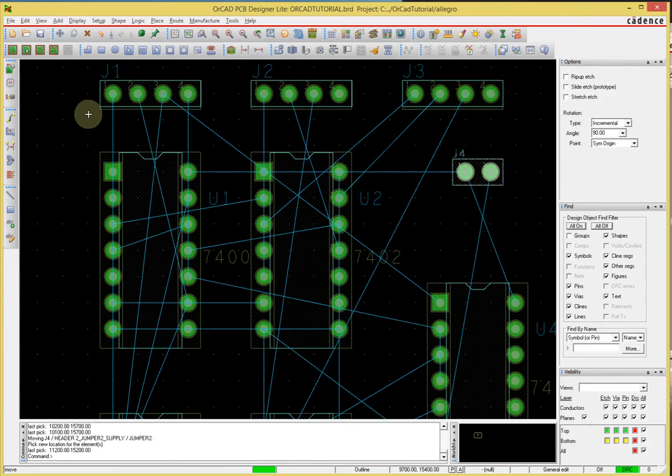And also you need to keep in mind traces. If I'm going to be laying traces around, I can obviously lay traces underneath the part, and we may need to lay some traces in between the parts. So you need to leave some spacing so that you can account for the possibility of laying out traces in between the two parts. So that's always to keep in mind.